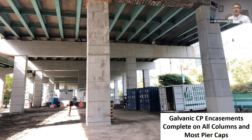And so inside all of these rehabilitated substructure elements is the existing reinforcing steel. The chloride contaminated core of those columns is still there, unfortunately, but the galvanic cathodic protection system is there to deal with the fact that you're leaving chlorides behind.